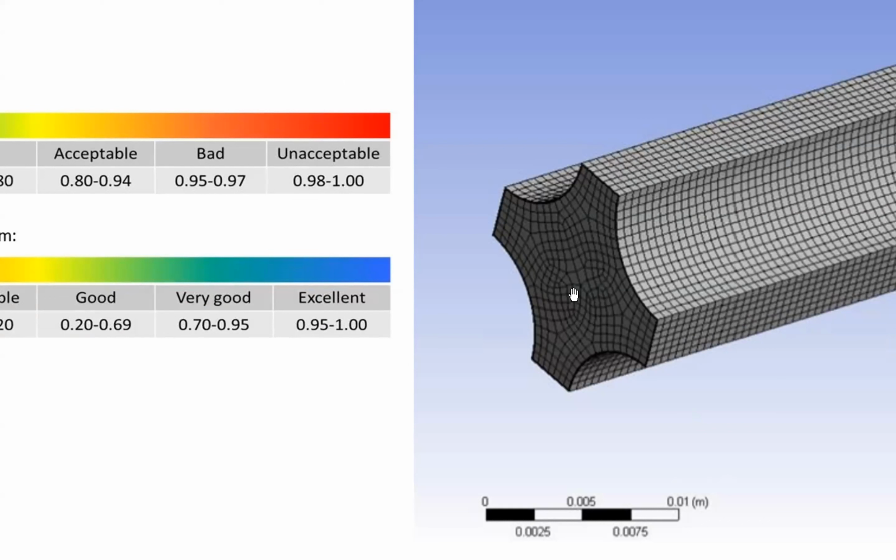We have some triangles, and we also have some quadrilaterals or rectangles. And if we look very closely here in the boundary layer region, we also have some cells that are in rectangle shape. We cannot see it from here. They are highly dense. So we can see that this mesh quality is quite good. We have very small skewness. These shapes are not distorted.